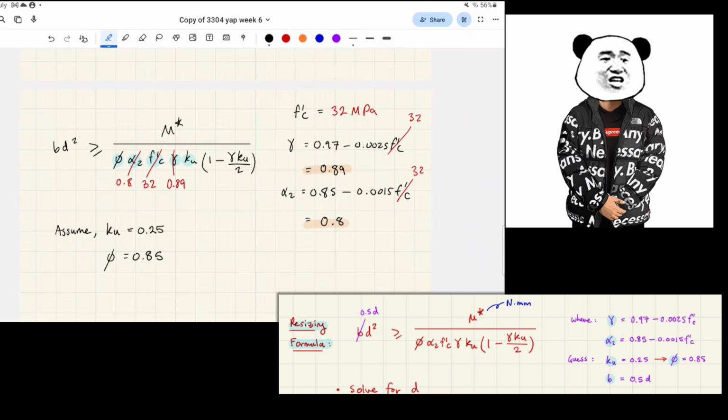Sorry, this is a stupid question, but would you ever design for a brittle section? At least in this course, I don't think it would really make sense. Maybe if you're not doing a building, say you're designing a pavement, it might save a bit of cost to design a more brittle section. I'm not too sure, to be honest. In this course, we design high stakes stuff like buildings, and we always design ductile sections.